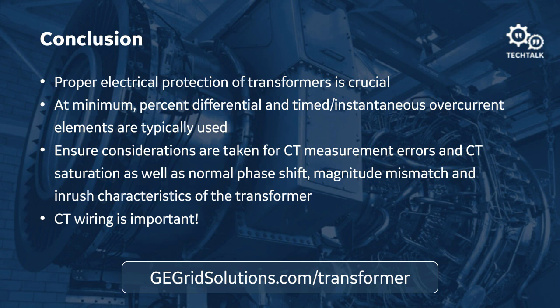So, you know, your second harmonic isn't going to pick up on that phase. If you're using the T60 relay and it only sees inrush on 2 phases, it'll automatically switch from 2 out of 3 to 1 out of 2 to make sure we still correctly block the differential in case the second harmonic drops low on one of the remaining phases.